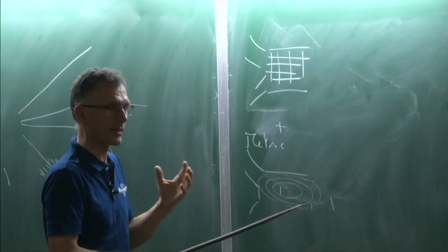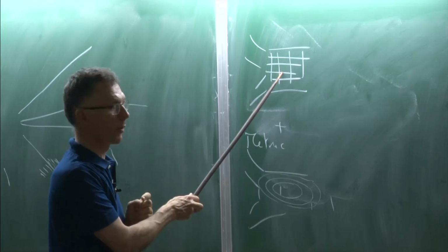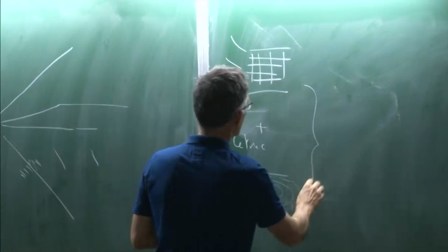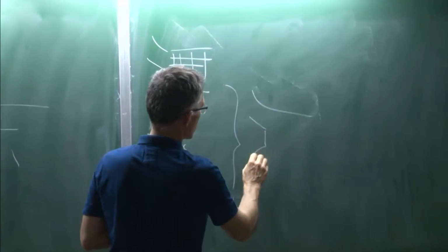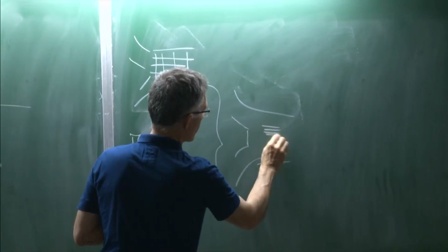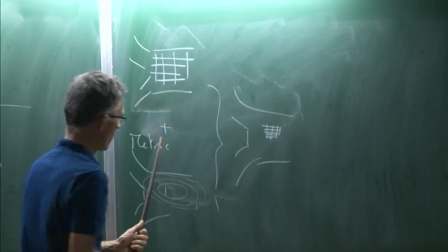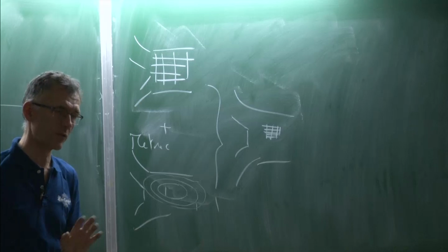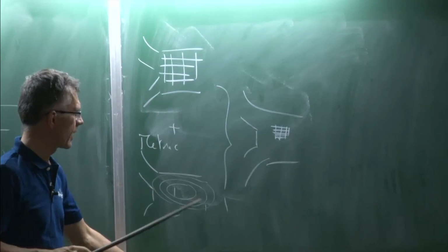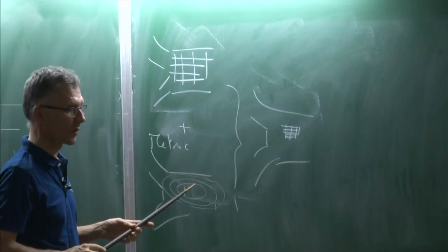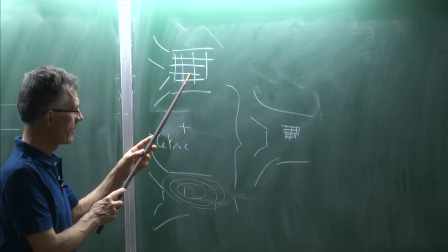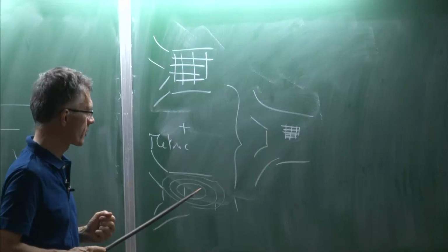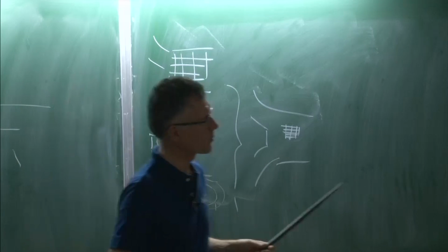The metric gives weight to the points here. And you're going to put these two things together, you will end up with a mesh which will look like this. It will be refined at the points where the metric was large. That doesn't tell you how to choose the metric. It's just telling you that you combine these two things, you give it the mesh you had, you give it a metric, it will give you a new optimized mesh so that you capture this metric better. So this is what's done here.